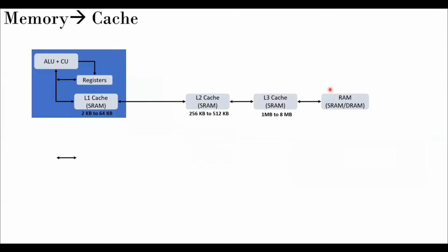Moving on, so we have the cache memory. So basically, for example, we have a single core system, I would say. So there is an ALU plus control unit here. Just outside are the registers. They have direct connectivity to the ALU, something like input and output also to the register. Then there is a bus system which is outside, which is coming, and typically it goes to the registers and then to the ALU. But nowadays, modern day machines, later they realized that you cannot keep on adding to the register number. Instead, I would add something known as SRAM into that, and they named it as L1 cache, level 1